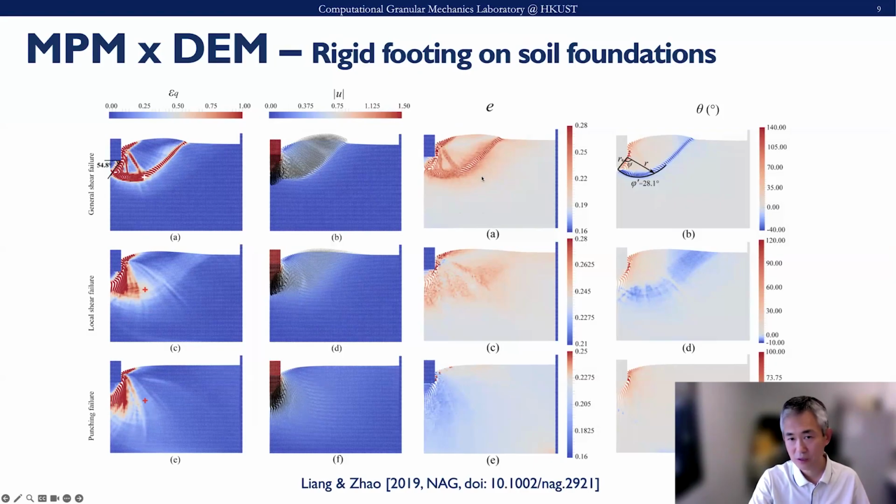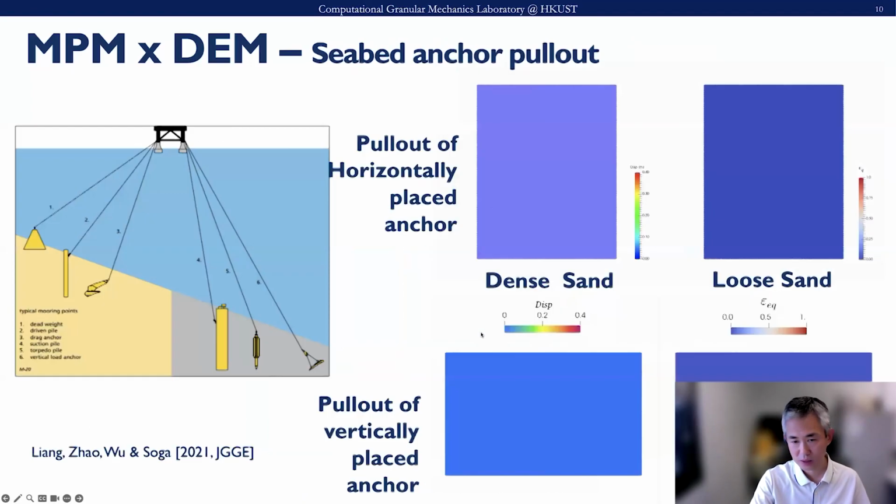And then we homogenize the void ratio in each RVE during the process or at the final failure mode, and this void ratio correlates with the shear deformation pretty well. Also, the cumulative particle rotation in each RVE can be well defined as an indicator of this shear deformation, as shown on the right. So theta is the particle rotation in each RVE, and this is the void ratio. This all correlates with classical soil mechanics or geotechnical foundation engineering theory pretty well.